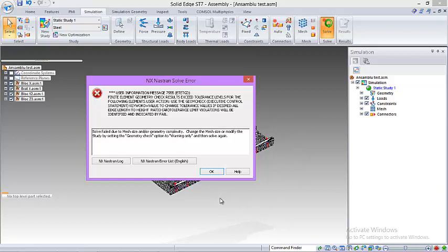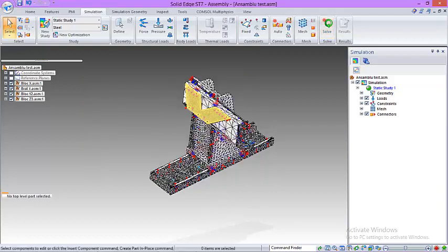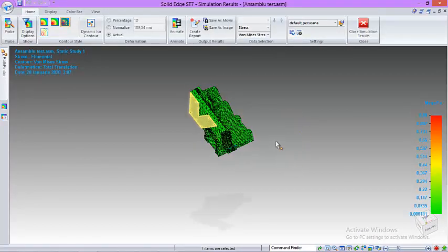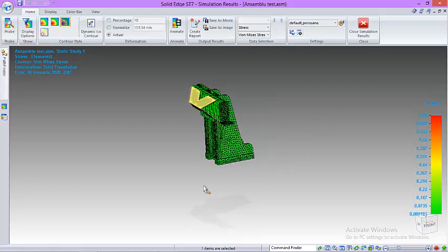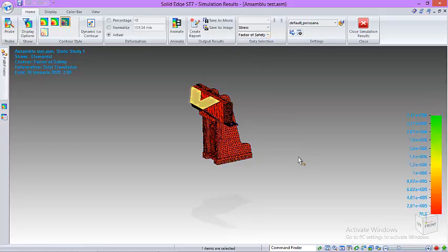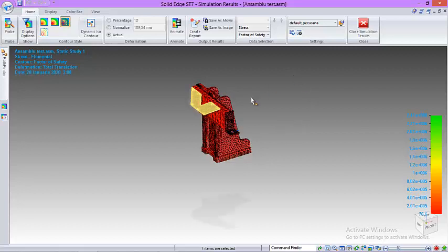I'm going to take a look at this and make sure this simulation is still possible. Okay, so I see that it can go without the base plate. I'm gonna try to get the base plate in also. If I can't, I'm gonna take a look at the safety factor, which is 76. It's pretty good considering we're applying 2 tons.